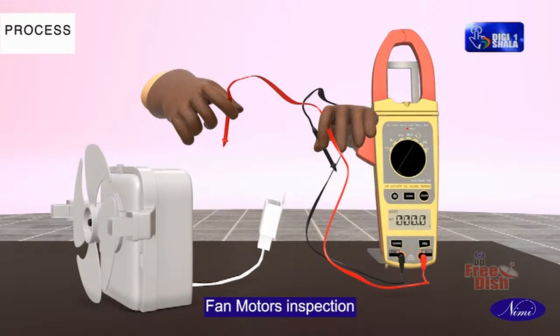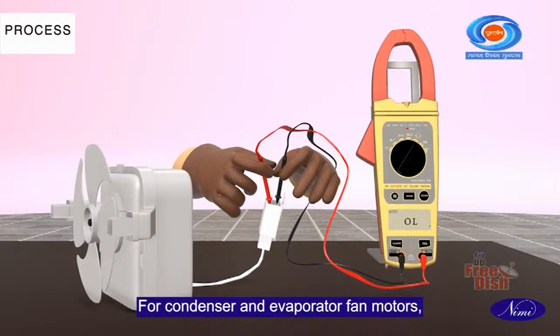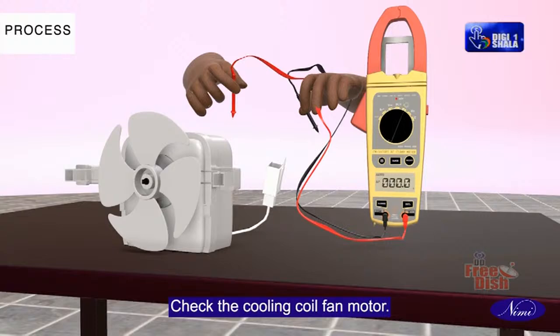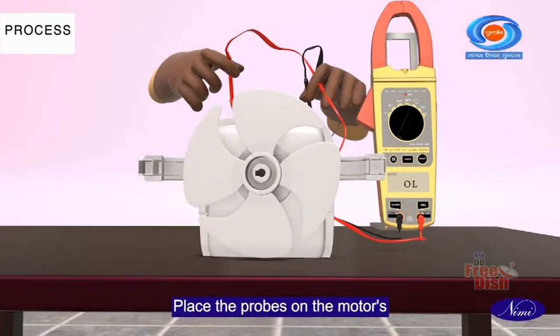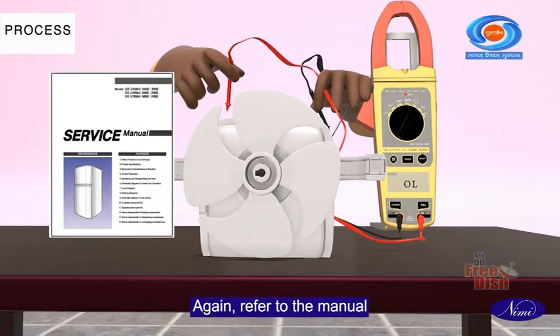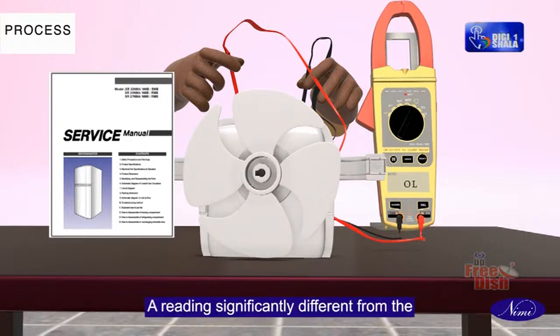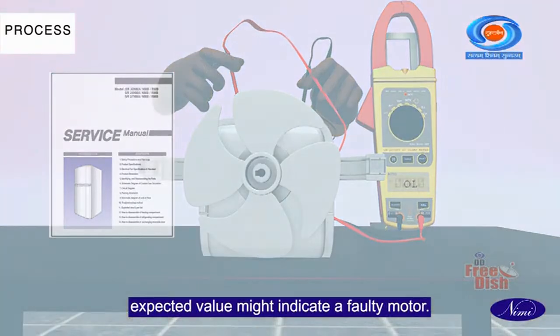Fan motors inspection. For condenser and evaporator fan motors, set the clamp meter to resistance mode. Check the cooling coil fan motor. Place the probes on the motor's terminals and check the resistance. Again, refer to the manual for expected resistance values. A reading significantly different from the expected value might indicate a faulty motor.